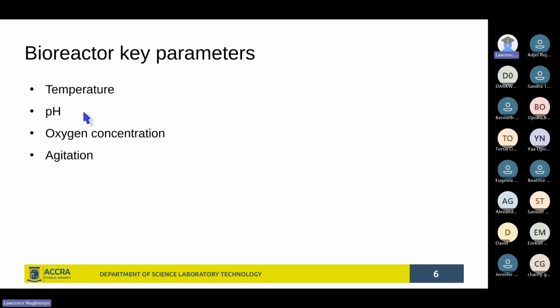Oxygen, as we just talked about, the process requires a certain optimum concentration of oxygen, so that if it's not controlled, it may result in clogging of the system. For instance, microorganisms could get overgrown, or maybe there is not enough oxygen in the system. Instead of an aerobic process ongoing, you rather have an anaerobic process.